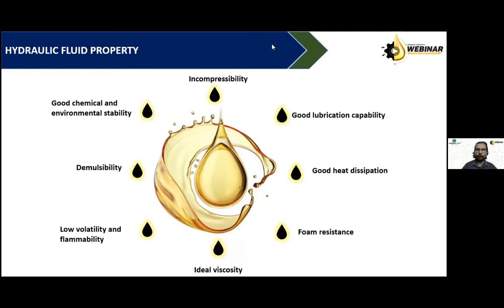Then we cannot keep our hydraulic system in a very safe place or within a closed area. Always it has to work in the field, so it should be robust enough to handle different weather conditions or tropical situations. It has to work under the rain or high heat, high sun, or sometimes temperature below 0 degrees Celsius or minus. So all these properties we should see carefully when we select the hydraulic oil for our application.